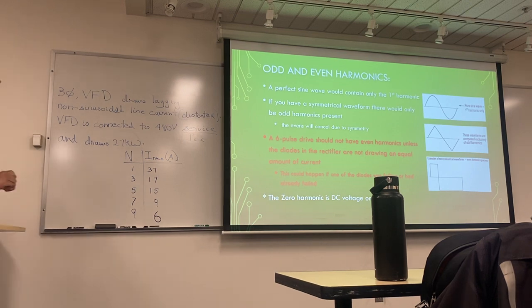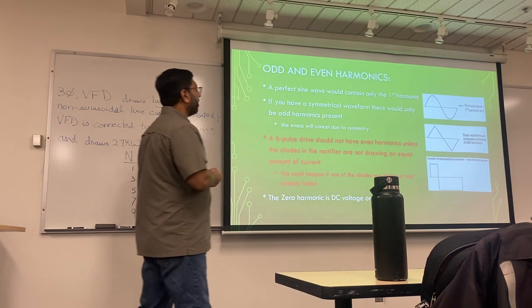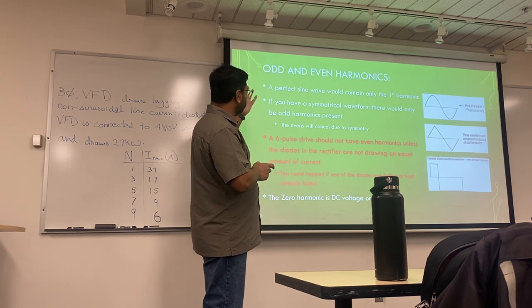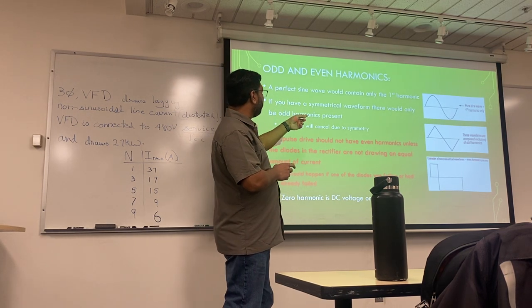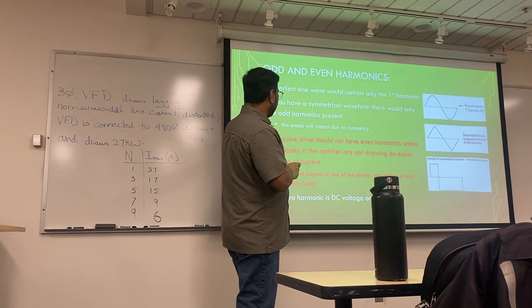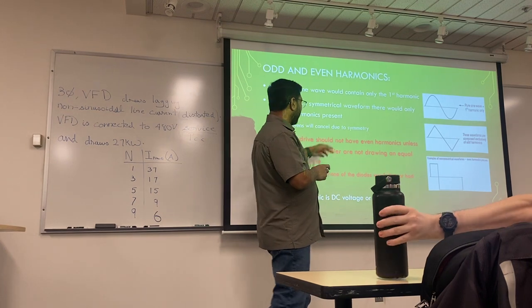So if you have a perfect sine wave, you only have one harmonic, which is your fundamental. If you have a symmetrical waveform, there would only be odd harmonics present. The even ones cancel out due to symmetry.